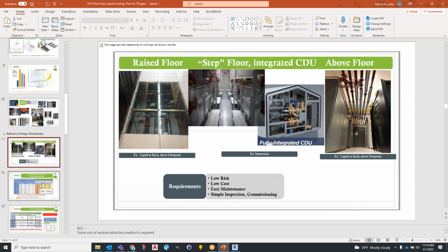If there's infrastructure that was put in overhead based on a 2.5 meter high rack, and you bring in an immersion tank that needs 2.6 meters, then it doesn't work, which means we haven't achieved the modularity that we're looking for on the facility side. And so understanding what those boundary conditions are is going to be a key thing.